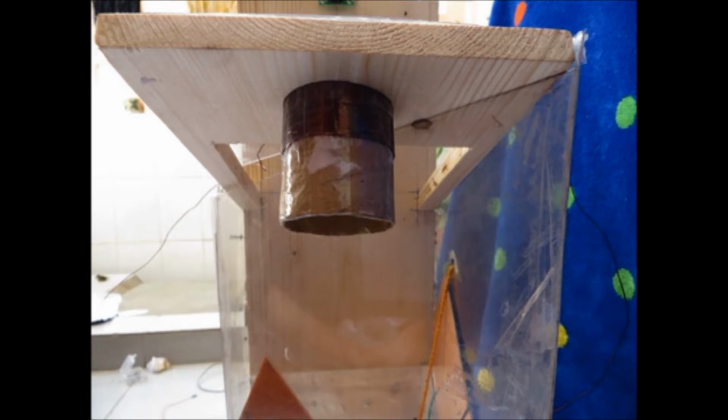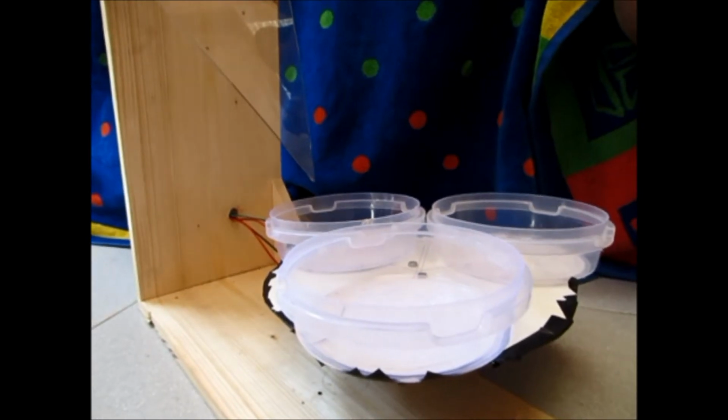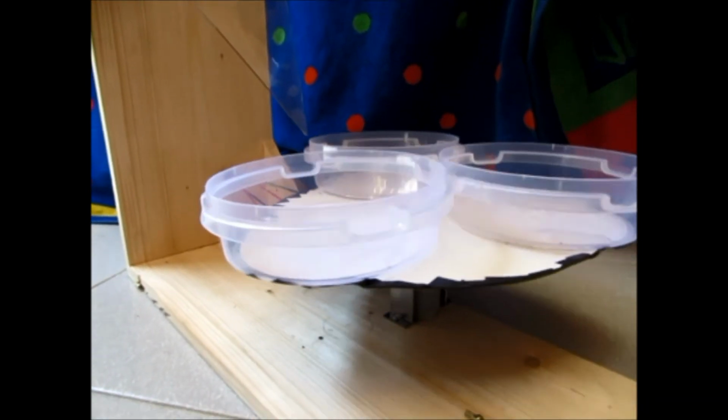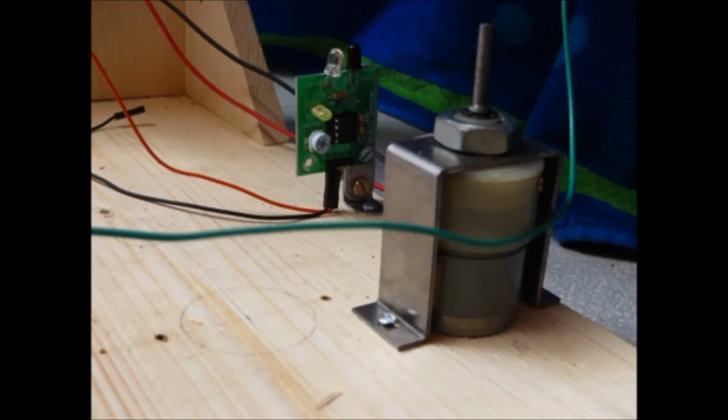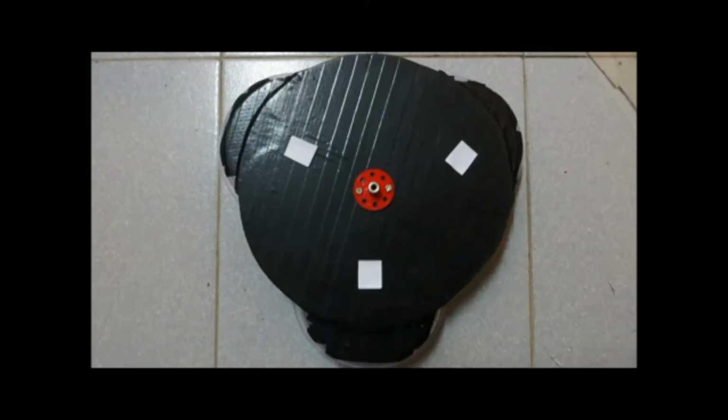From there, we move on to the capacitive sensing system to distinguish between biodegradable and non-biodegradable waste. On the identification of the origin of waste, the circular panel rotates so that the appropriate bin comes to rest under the capacitive sensors. The capacitive sensing system also has a collapsible base so that waste falls down to the appropriate bin. The rotation of the circular panel and the collapsible base is controlled by DC motors and IR sensor modules.